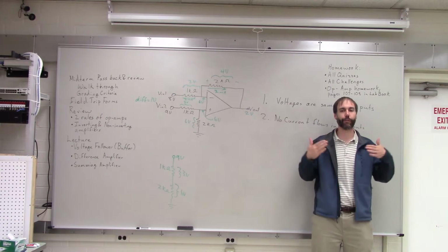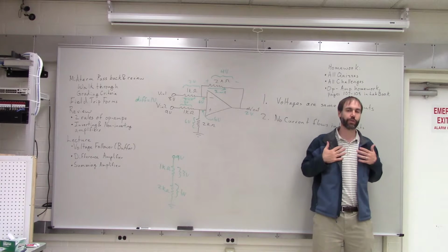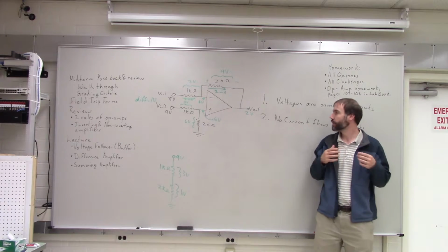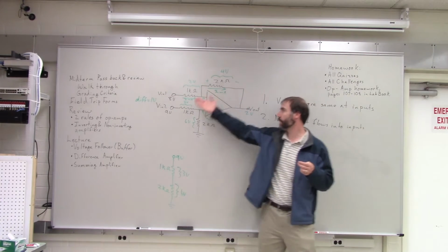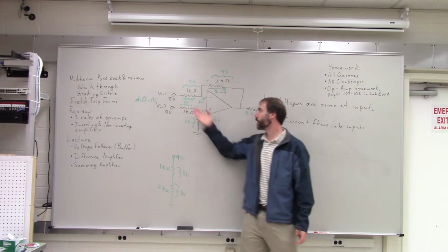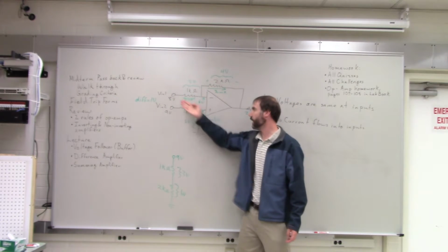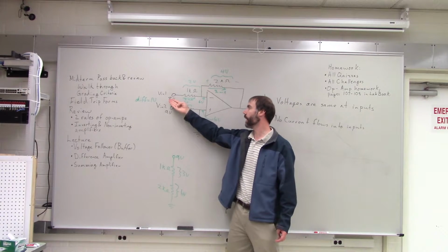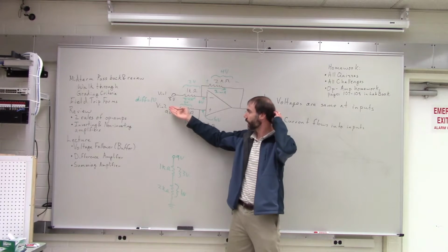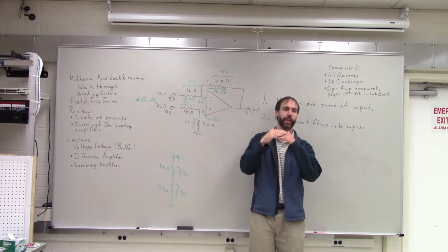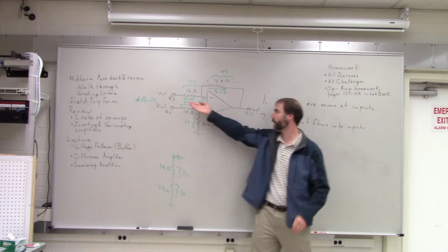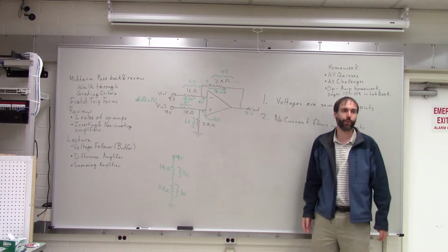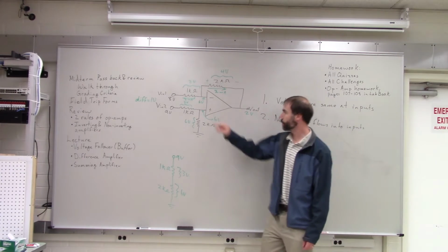What you care about is the difference between them, like the difference between the voltage on one side of your heart and on the other, because that's what's causing it to beat, right? So you would use a circuit like this, and this gets rid of the common voltage, right? This didn't care that one was at 8 volts and the other was at 9 volts. All it cared about was that the difference between them was 1 volt. Okay, so if this had been at 99 and 100, this still would have given us the same output. So it's really just looking at the difference.